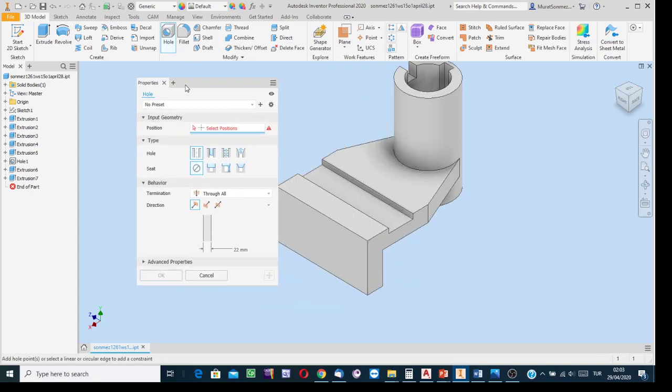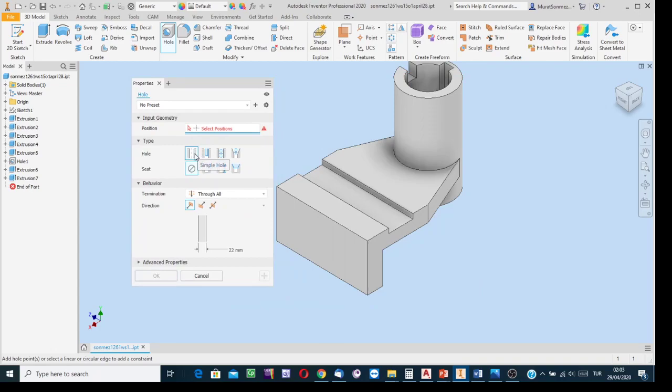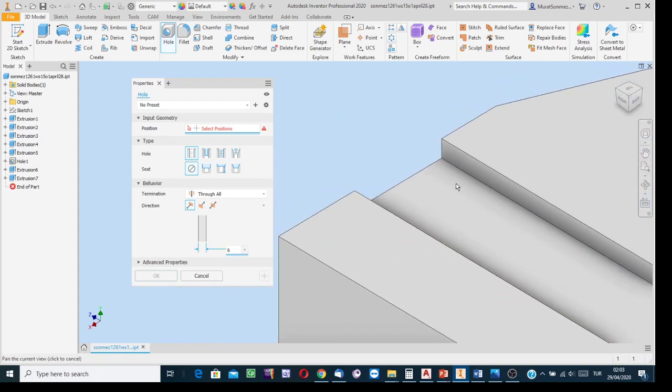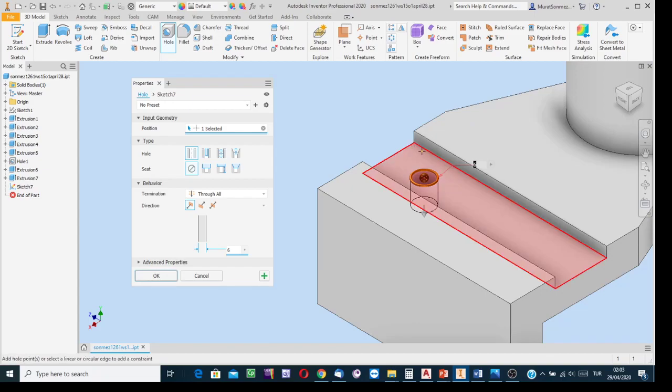And then in the dialog box, I know it is a non-standard tool, so select this one. It is truly extending. In the box for the diameter of the hole write 6, and then the rest. First indicate the starting surface of the hole, and then indicate the reference feature. It is this intersection.